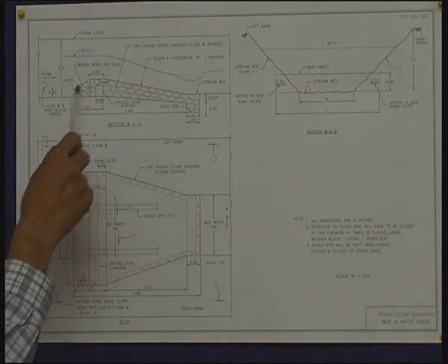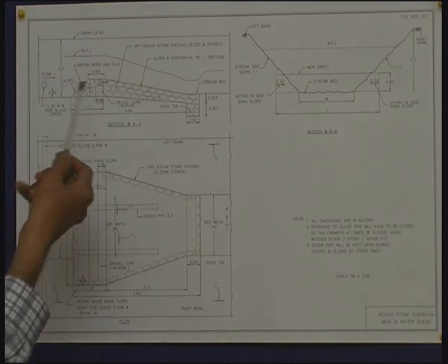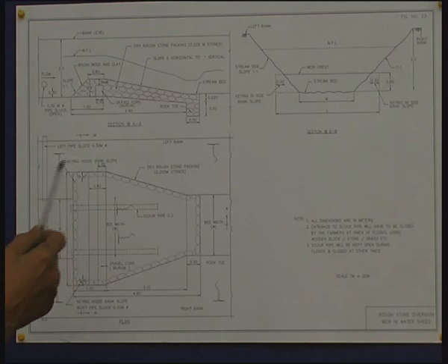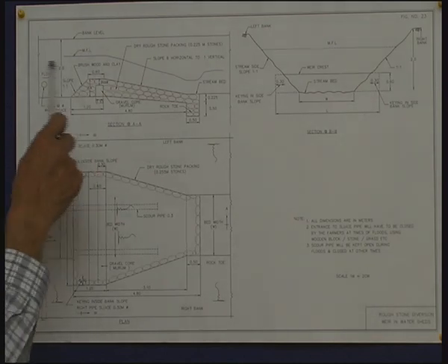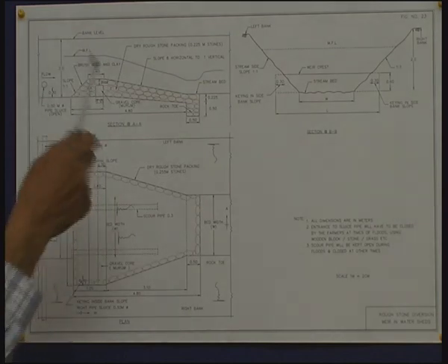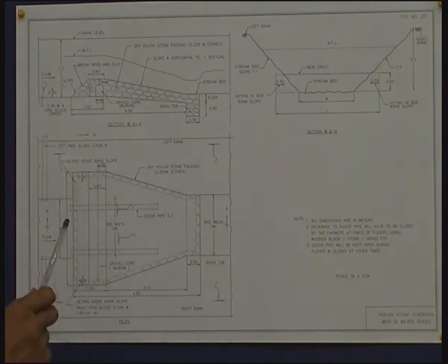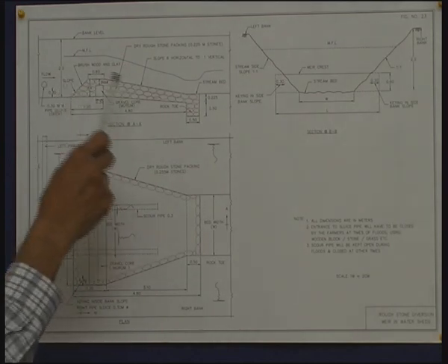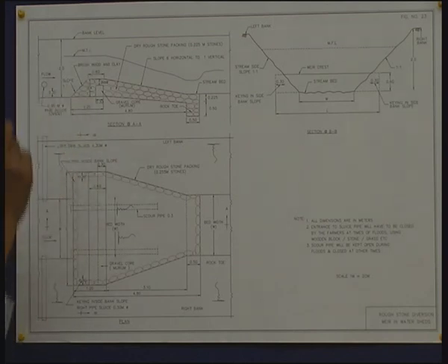Such a small structure may be having a length of about 50 meters or 20 meters or whatever it is, depending upon the bed width of the stream. And whenever a flood of this dimension occurs, this gets breached because it is not well designed hydraulically. A small rubble stone structure like this would breach when a high flood comes.